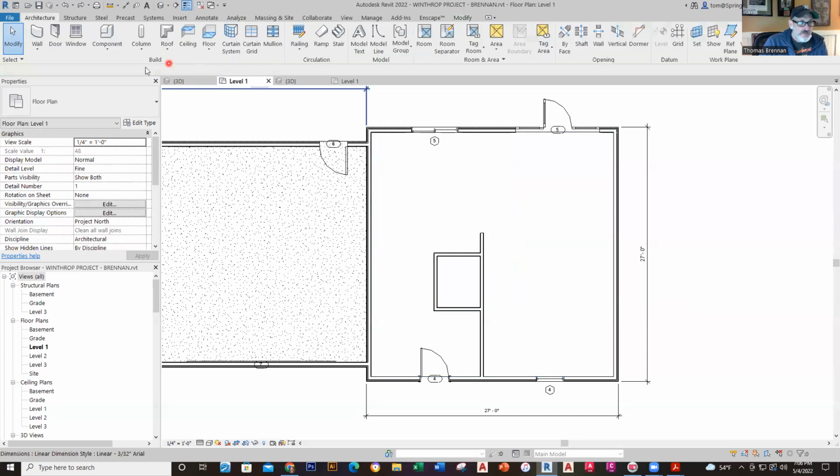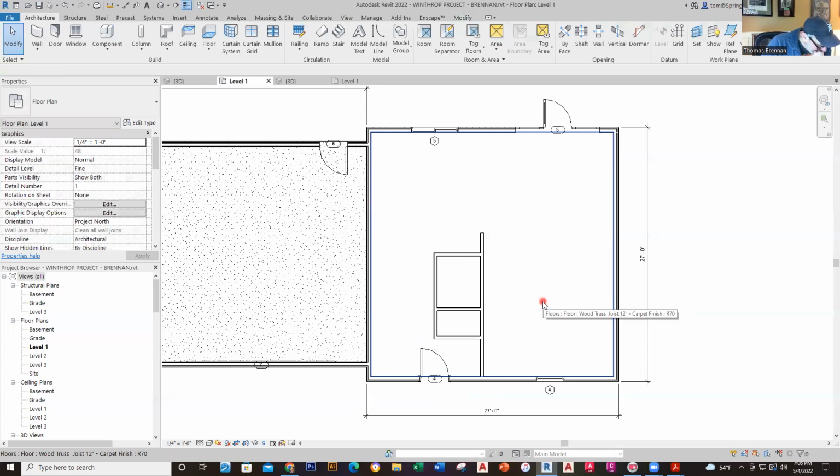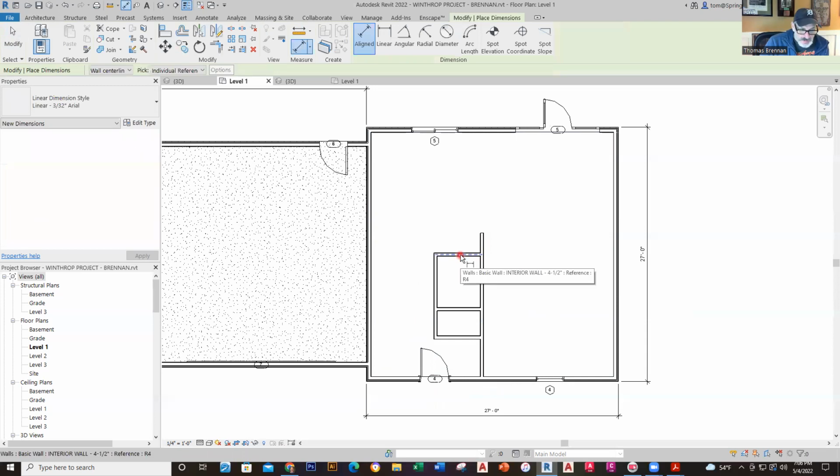We're just going to put another wall in here, and then we'll move the whole thing. So go down to here, and down a little bit. So I got that. Now that's going to be 6'1". I'm going to put a couple dimensions on here, make sure it's what it should be. So go from here on the inside. That should be 6'1", and it's not. I'm going to take this wall and move it down.